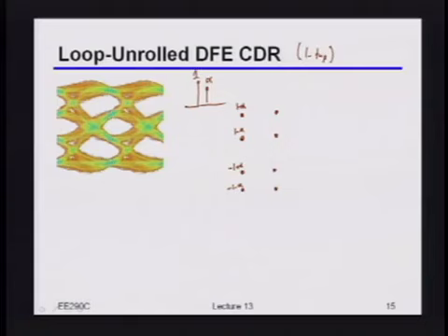The thing that's sometimes initially confusing to people is that this alpha, whether it's a plus or a minus, is correlated with what the value of the previous bit was. So you can't just draw lines from each of these possible points to each of the other possible points, because not all of those can really happen.